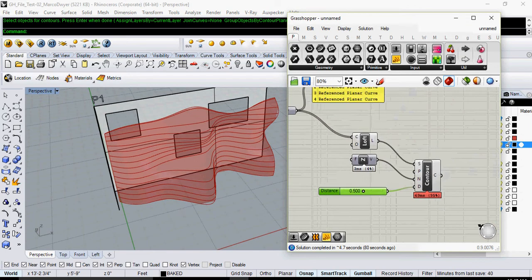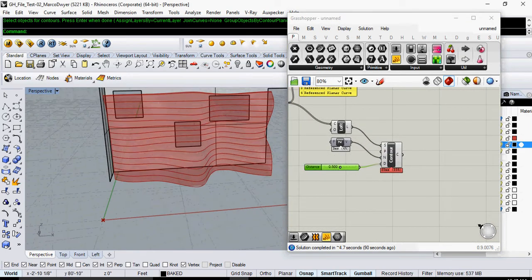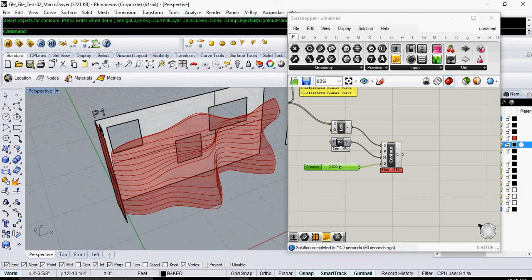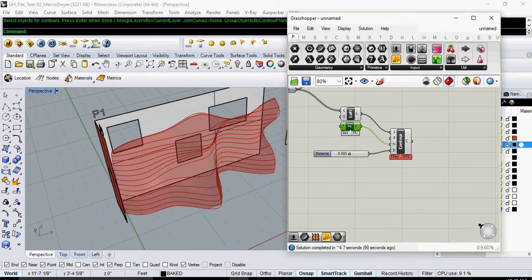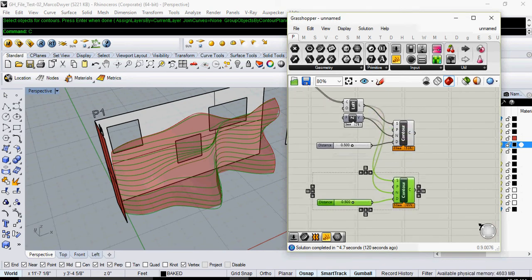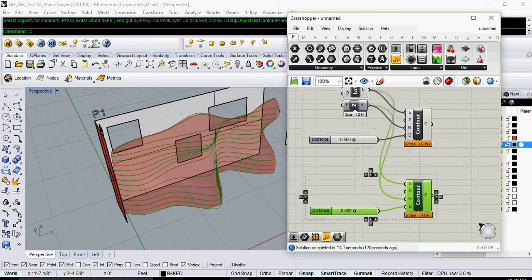The next thing you're going to do is make a contour in another direction, cutting it in the opposite direction, so it's actually creating these cuts. We can copy this contour by clicking on it. I also want to copy the distance, so I can hold shift and click on the distance, then Control C, Control V, and I just pull it down. Be careful: you might hit Control C, Control V and click out of it by accident, and you're going to have just these two. In this case, it's easy to click on both of them, but in some cases you might have a lot more. So be careful after copying.